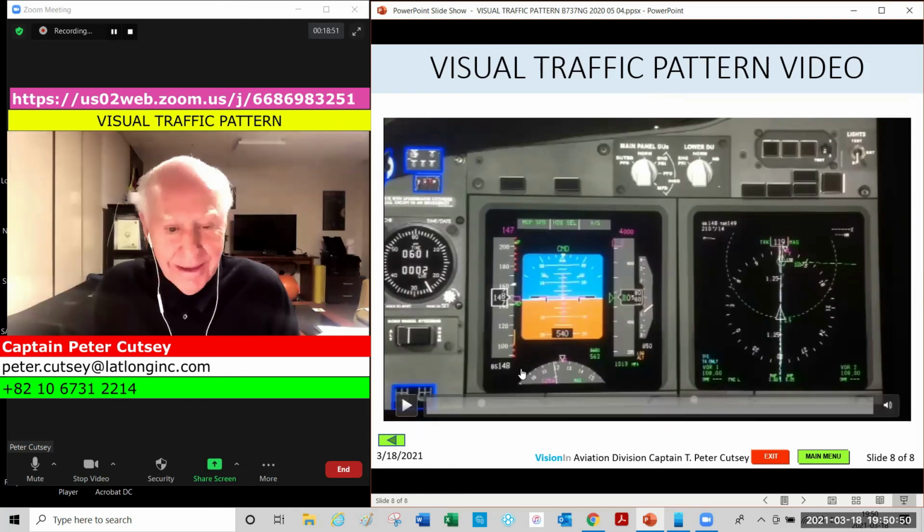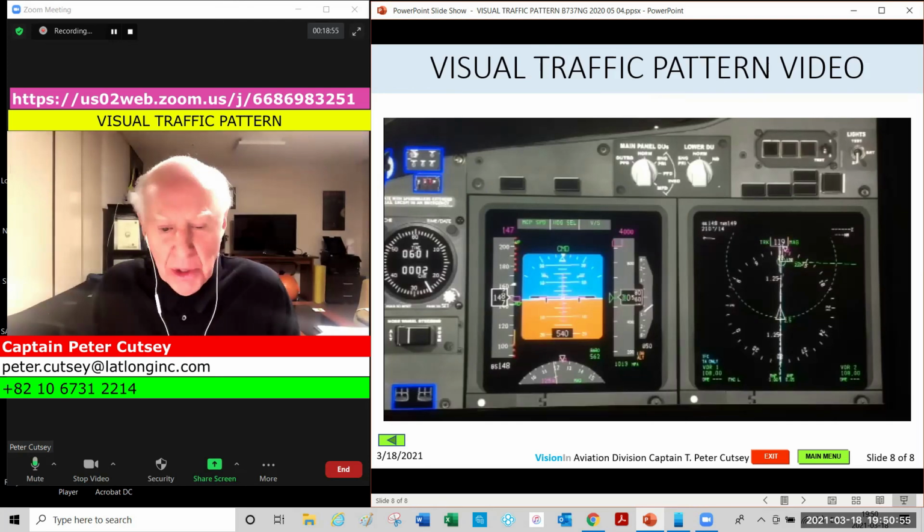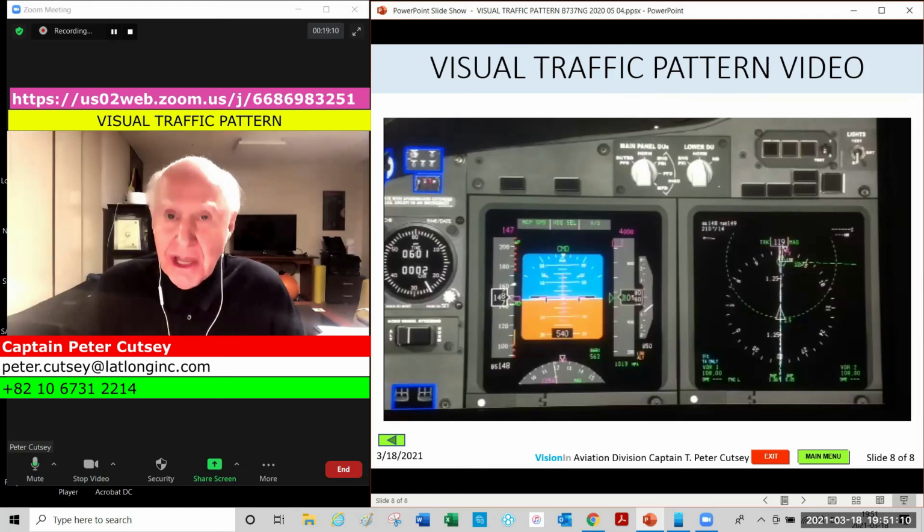Okay, so there you have it. I hope you enjoyed that. One comment I made in the video, which I'm going to correct right now, is you don't start turning any sooner when on base leg. Wait until the trend vector touches the extended center line. The noodle, or the 30-second trend vector, knows the wind, knows the ground speed, knows everything. So you use the tip of it when it touches to start your turn, and the rest of it, as you can see, turns out very beautifully.